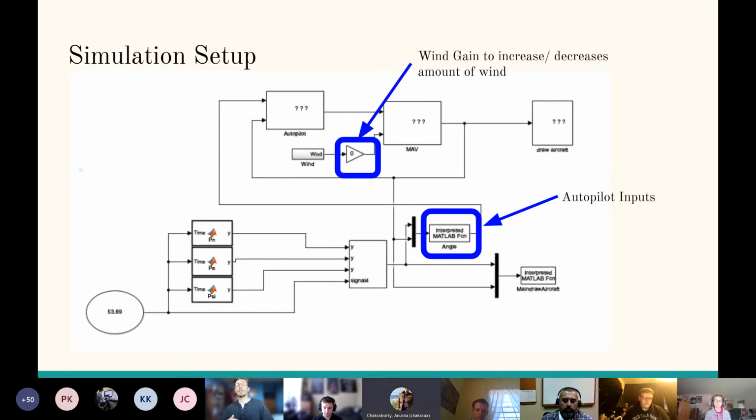We thought, what's a pretty good glide slope for an aircraft to land on a deck, and then we played with that to see what the PID would do and how it could successfully do it without making really sharp turns or being too high and then having to nosedive to the deck. So we just played with those numbers till we got a good animation. We had pretty smooth values. Okay, thank you.